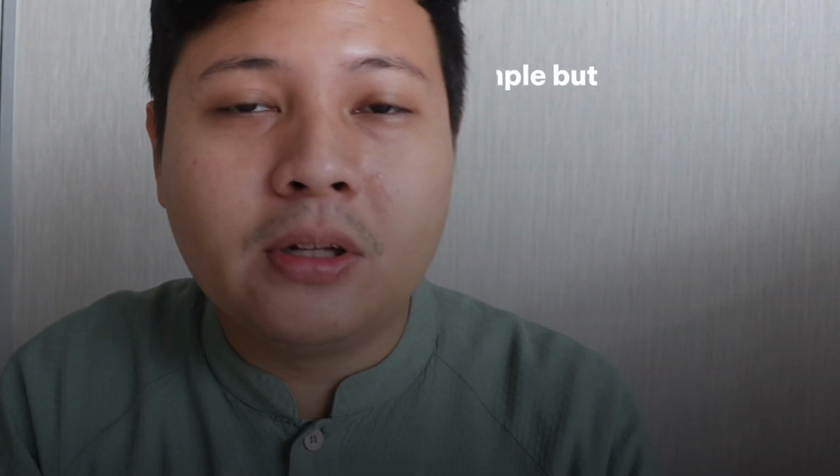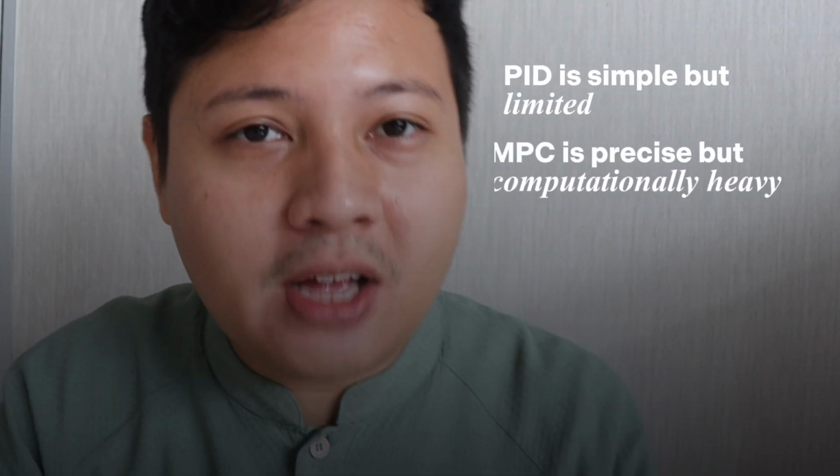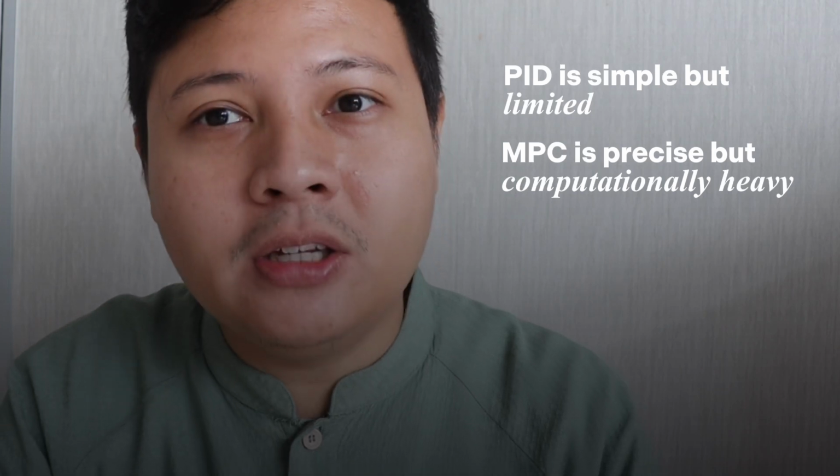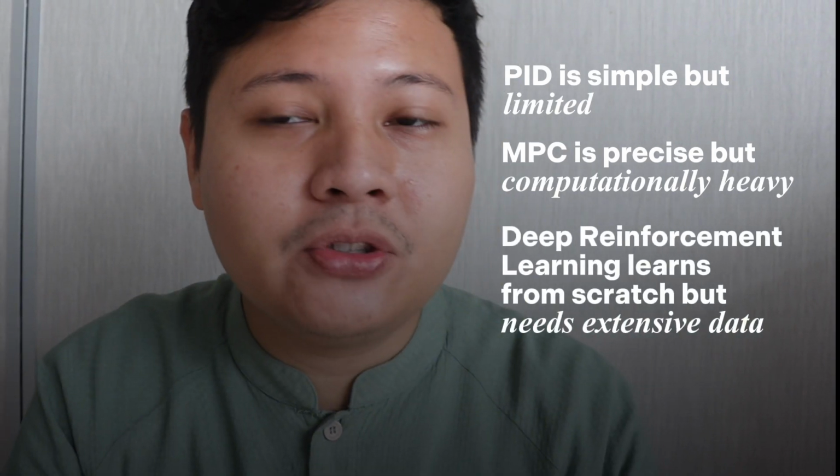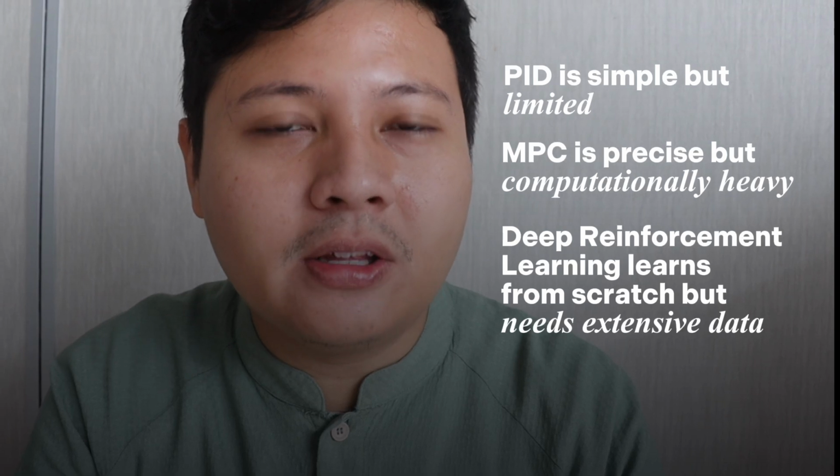Each method has strengths and weaknesses. PID is simple but limited. MPC is precise but computationally heavy. And DRL, deep reinforcement learning, learns from scratch but needs extensive data and high computation as well. Choosing the right one often means balancing these trade-offs.